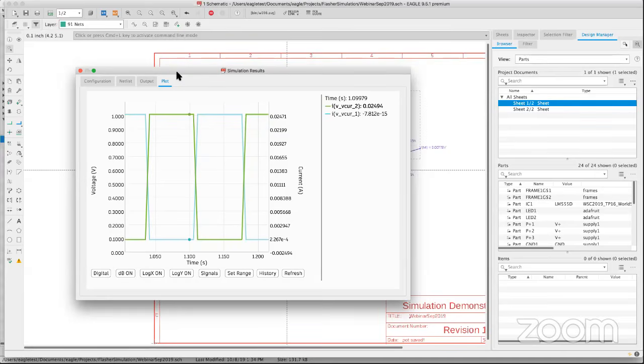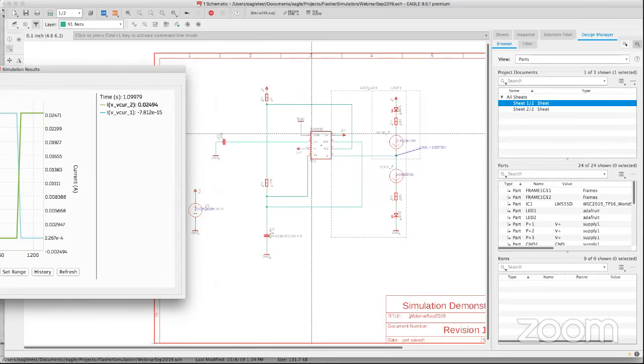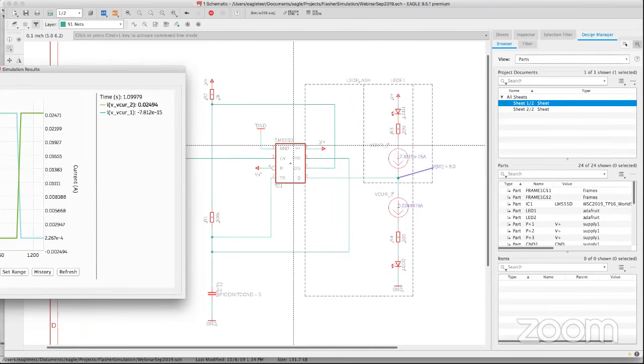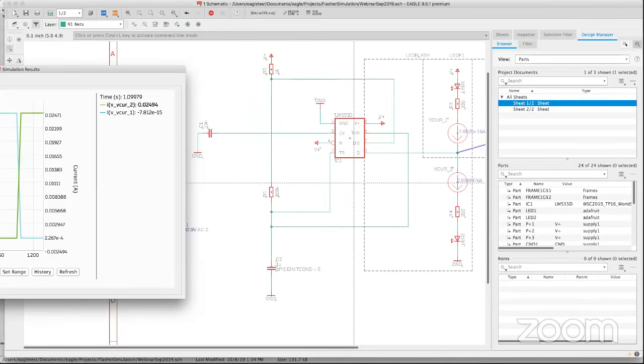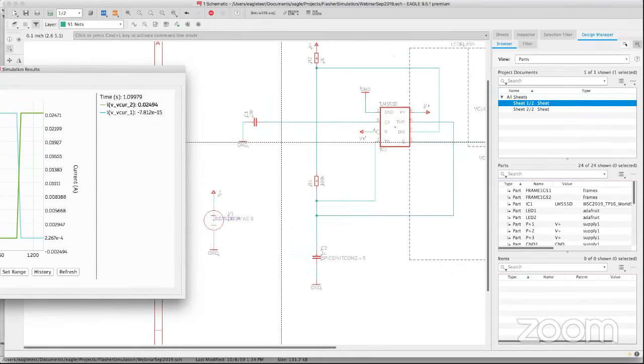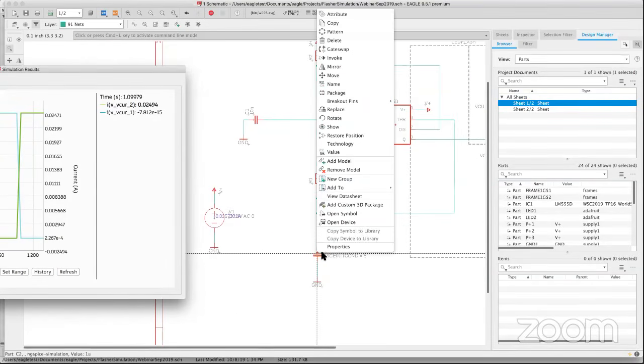By the way, in this simulation, it's very important, Ed, if you can show them on the capacitor, there's an attribute there called spice init condition. The initial condition of that capacitor is very important. It needs to be at some voltage initially, otherwise the simulator chokes on it. So if you can show them how to define attributes, Ed, that'll be helpful because I know Mark is asking about that as well. Okay, very well.